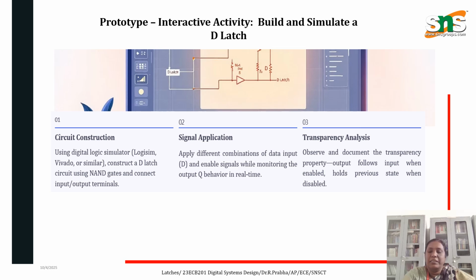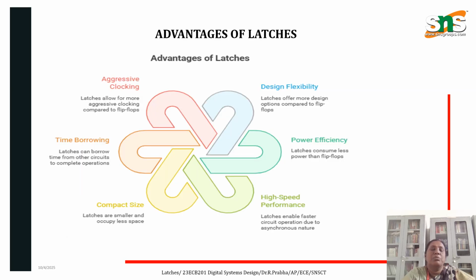Now, advantages. There are many advantages of latches. Design flexibility is very simple when compared to flip-flops. Power efficiency: they consume less power. High speed performance, because it is level triggered, and aggressive clocking is allowed. Time borrowing: they can borrow time when other circuits complete operations. And the size is very compact.